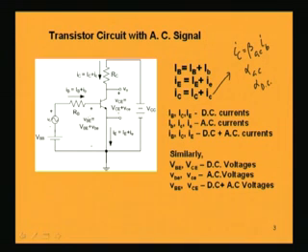So, you have to notice that this is the biasing voltage, but the base to emitter voltage is not the same, because the base to emitter voltage is obtained after the drop occurs here. That is, this voltage minus this drop. The drop occurring across RB is because of this instantaneous current IB. So, this voltage minus this drop is equal to VBE.